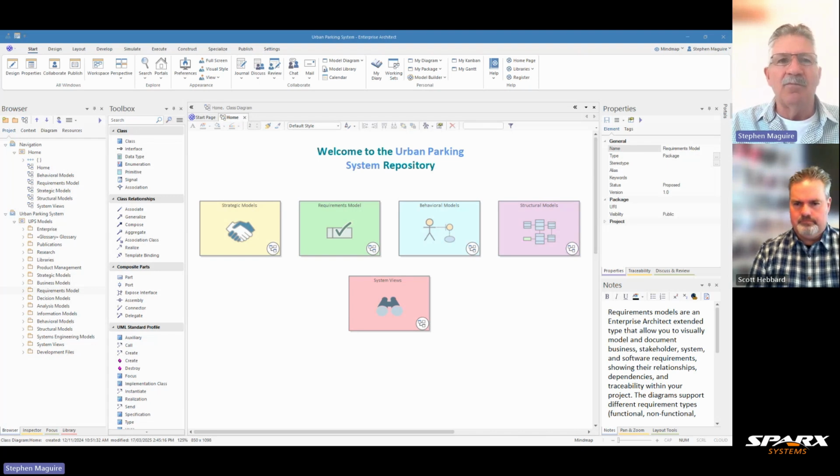The requirement may satisfy a function that a system must perform or a performance condition a system must achieve, and SysML provides modeling constructs to represent the text-based requirements, and then you can relate them to other elements. So we do have a requirements diagram where we can see the requirements in their totality, but also the requirements can appear in other diagrams where they relate to things like blocks or activations in a sequence diagram or states.